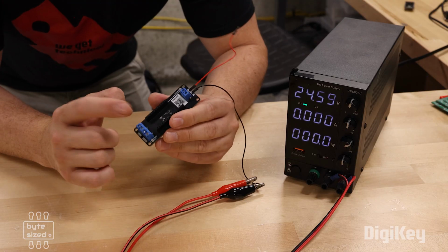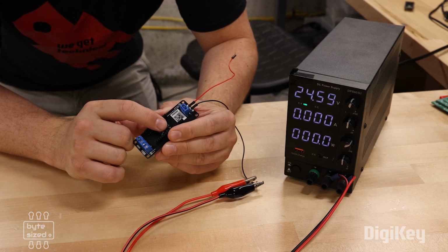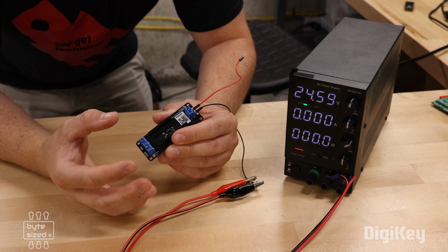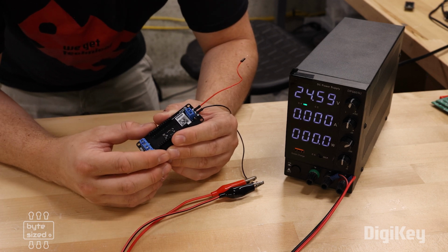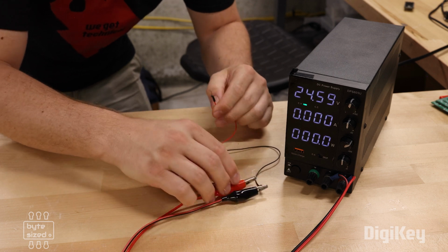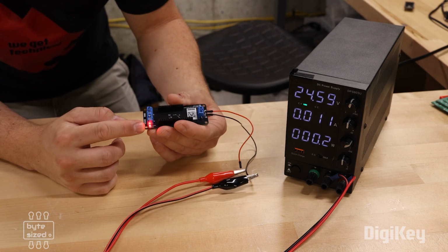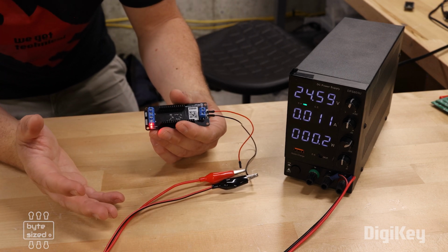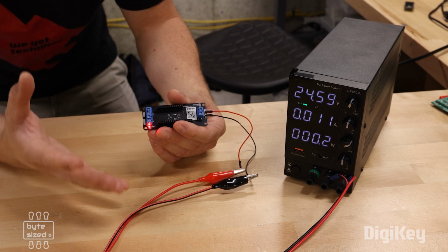I think the solution is pretty simple. I just need to add a 10K resistor in parallel with the lower half of that voltage divider, and I think the fault should go away. Okay, now I have that 10K resistor soldered onto the board, and it's pretending to be the battery temperature thermistor. When I plug it in, I expect that charging light to turn on. The charging LED has turned on, which tells me the MPPT chip is working, and I can keep moving forward.